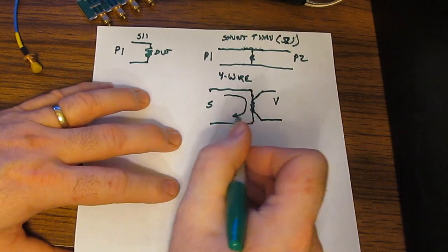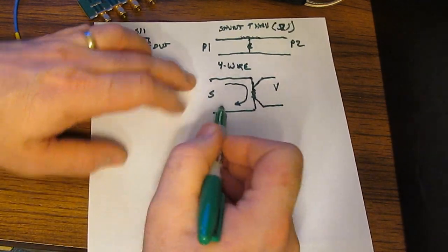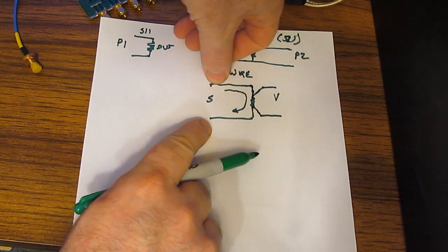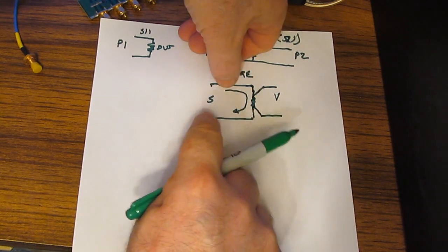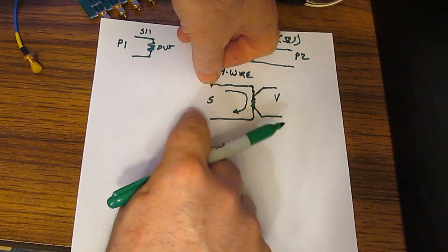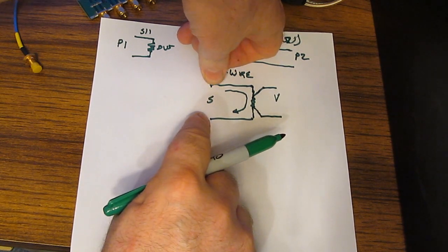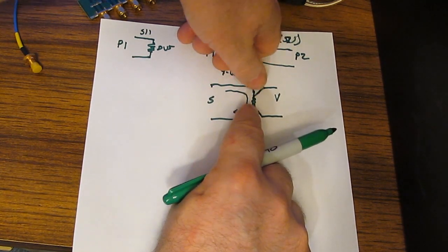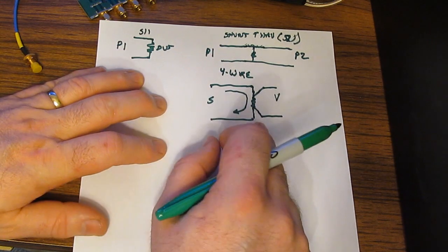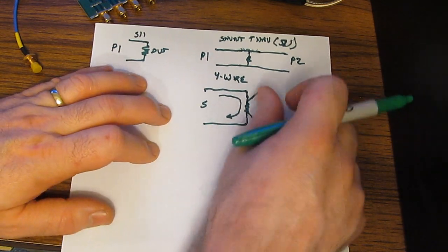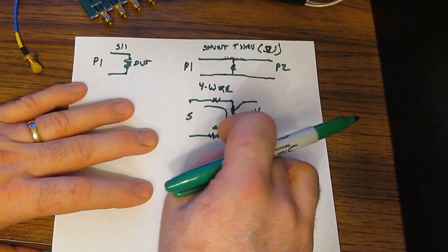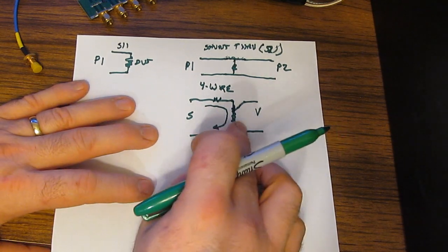And the nice thing about this is where normally a multimeter is measuring back at these points here, and these would be your test leads. You have all the losses of the leads, the connection points back here, the connection points to the DUT that you have to deal with. So for low impedance measurements, that doesn't work very well. Using this technique, we can actually get a very accurate measurement.